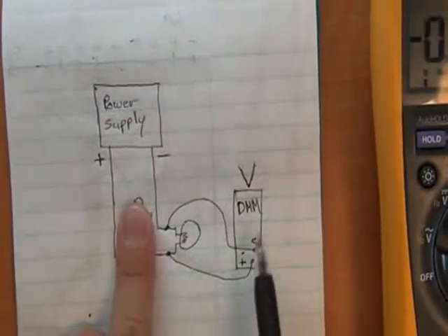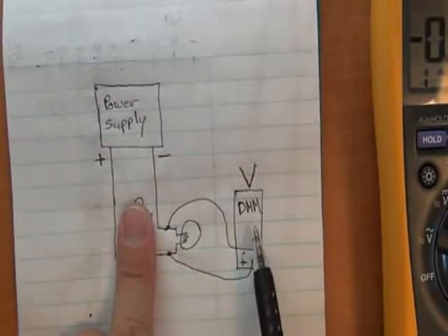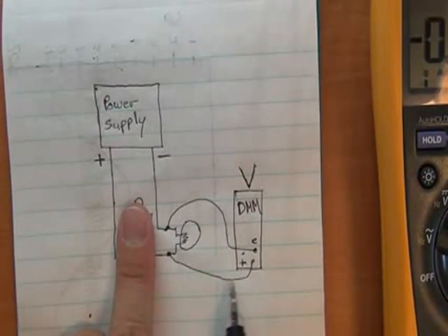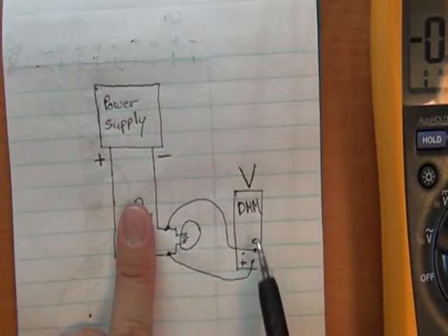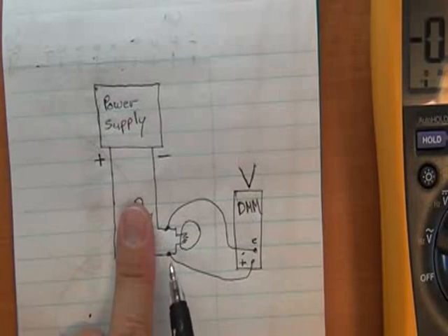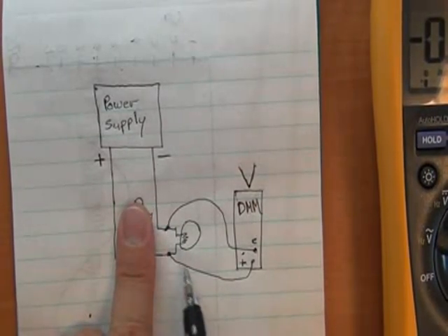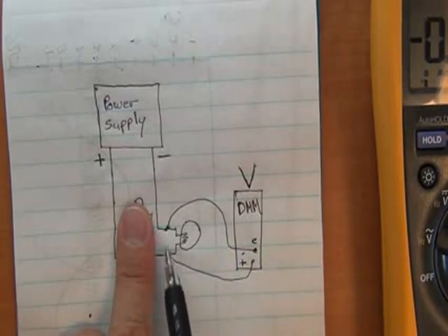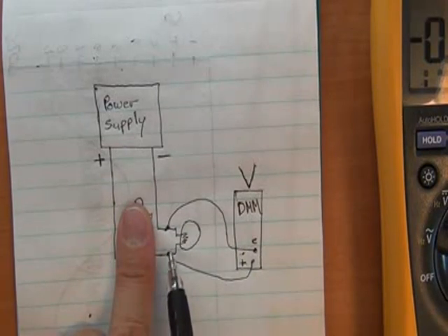Your digital multimeter, when you've got it set to volts, has a very high resistance, so it doesn't allow much current to flow through itself. It is minuscule, and remember, it's like that little pressure gauge in a pipe. It's just tapping in to measure the pressure. So in essence it's not really forming part of the circuit at all.